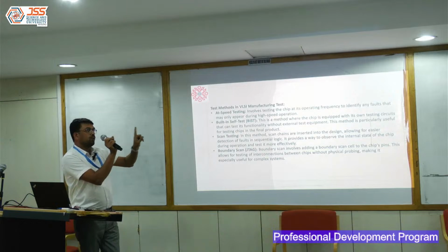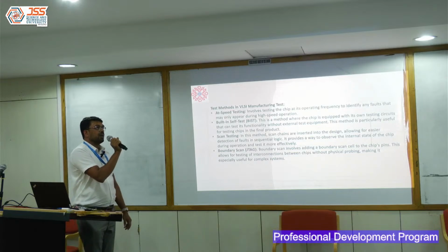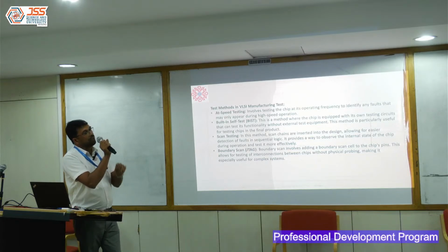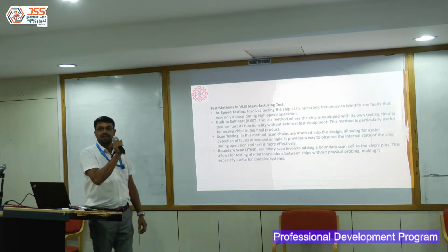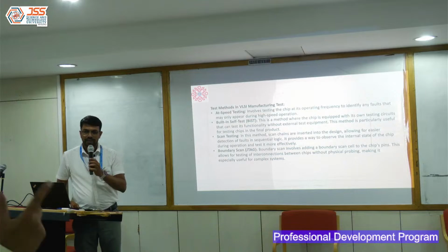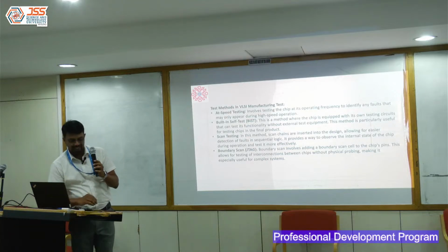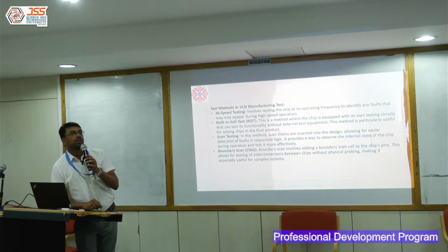If I move the clock edge again, the same condition will be there. So you cannot work around hold by increasing or decreasing the frequency. Maybe Vijay sir can give you more details. So that's one of the basic requirements when it comes to timing closure. You have to fix the hold.